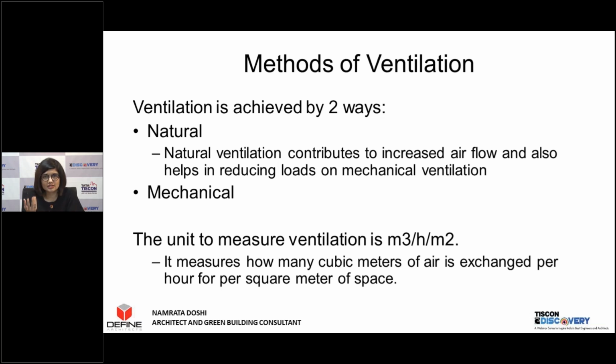If you're doing this by natural means, you're going to understand how many openings you have, the surface area of the openings, and how much air it's going to give you, and accordingly design your openings. If you're going with the mechanical method, you're going to then calculate how much tonnage you are going to need for your mechanical ventilation to fulfill this requirement.